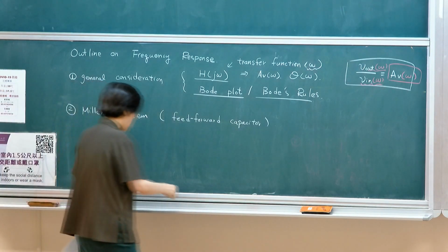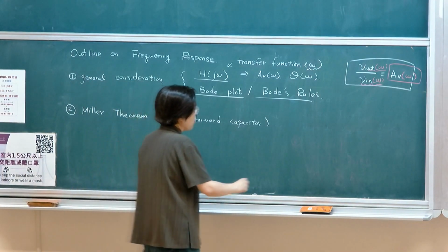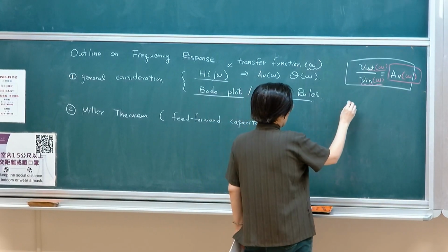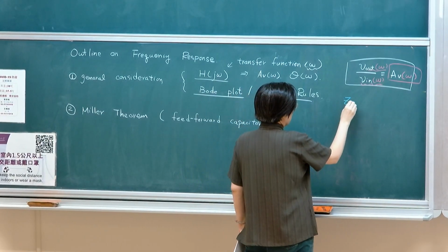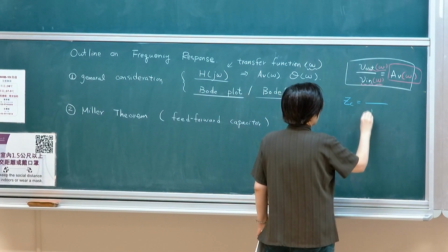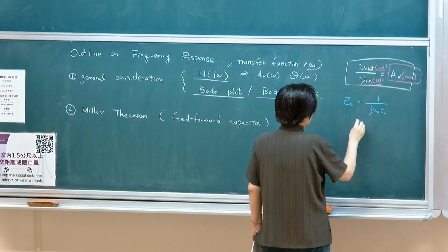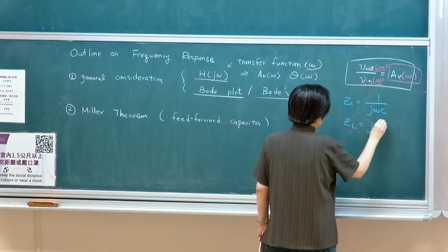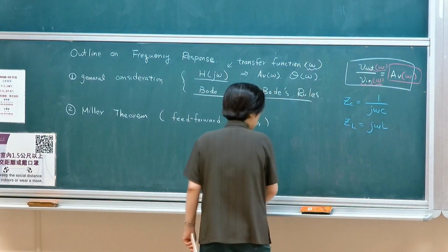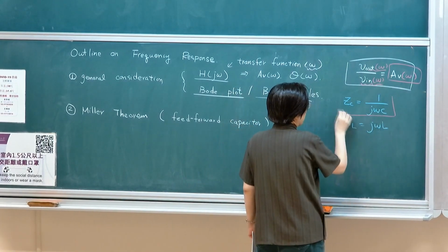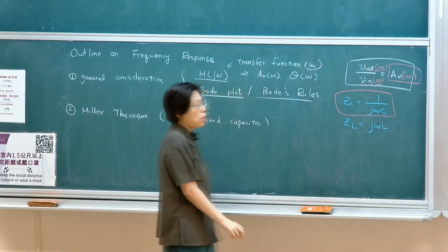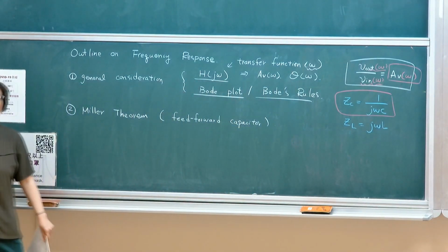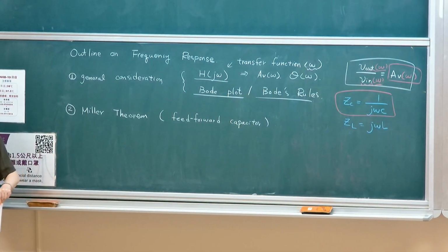So when we want to discuss these frequency responses, most of the components we actually discuss, there's two components. Everybody knows that it has frequency dependency: for a capacitor, ZC, which is 1/(j omega C), and for impedance of an inductor, which is j omega L. But in this discussion, we'll probably limit ourselves mostly on the capacitive components, which mainly happen in lower frequency.